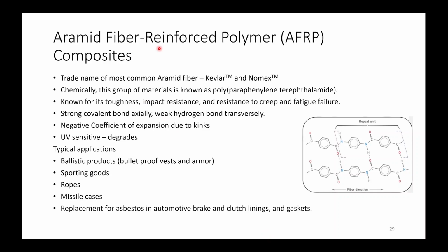Now aramid fiber reinforced polymers. The trade names of the most common aramid fiber are Kevlar and Nomex. Chemically, this group of material is known as polyparaphenylene terephthalamide, and it is known for its toughness, impact resistance, and resistance to creep and fatigue failure.